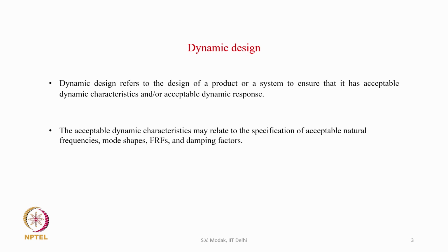Another requirement could be associated with the desired mode shapes. We may like to have, let us say, the node of a mode at a certain location. We may like to locate anti-resonances at certain frequencies, so that the responses at those frequencies are small. We may like to have desired damping factors, and we may like to increase the damping factor in certain modes. This could be the definition of desired dynamic characteristics.